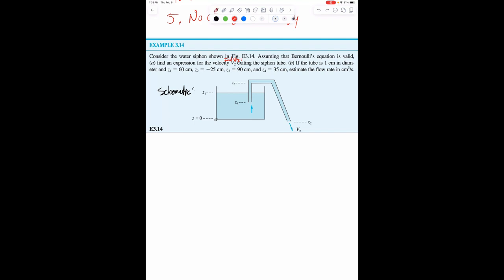So in this problem, I see at location 1, that's the surface of the water sitting right in front of the atmosphere. Therefore, it's experiencing atmospheric pressure at that location, just atmospheric pressure. No fluid column height or anything, just that. And same for the exit of the straw, because when the fluid exits the straw, you're back at atmospheric pressure.